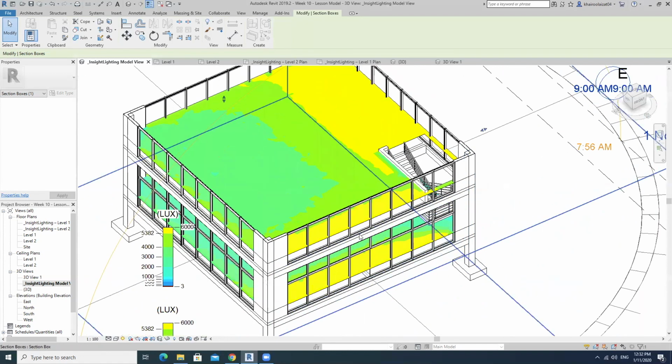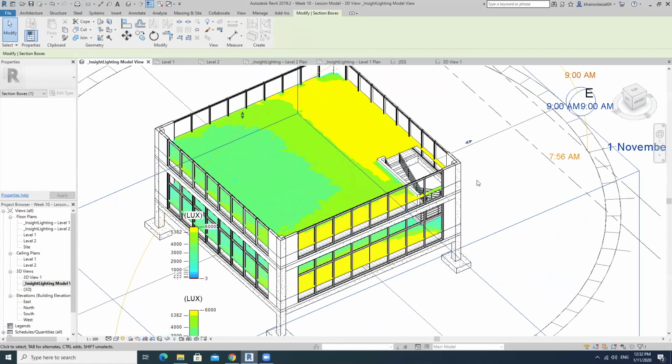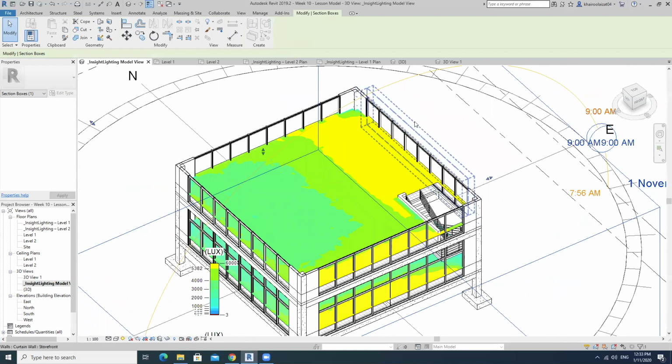Maybe you want to add some sun shading. So this is where we want to see how you actually strategize by proposing certain passive design strategies in order to control the light intensity into your space. Okay, so as you know by now, different spaces require different illuminance levels. So in this case, how you design your facade as well as your building layout, in order to control the amount of light into your spaces.